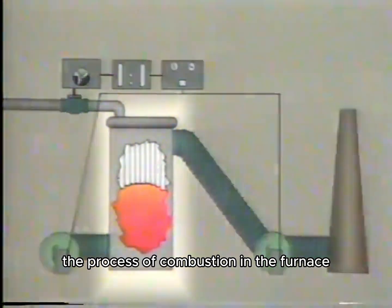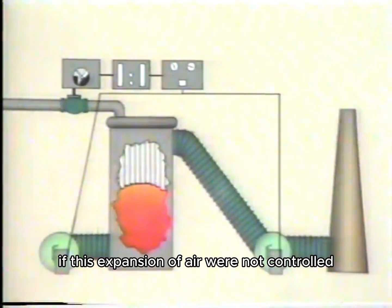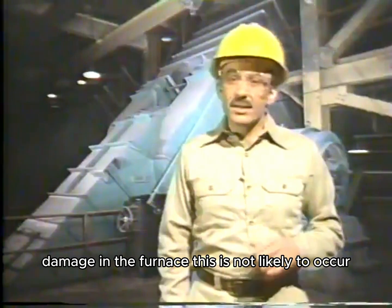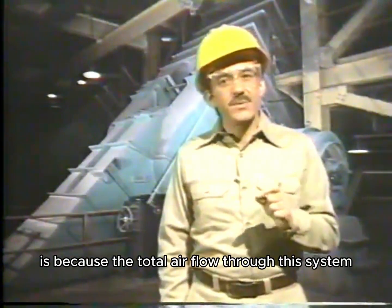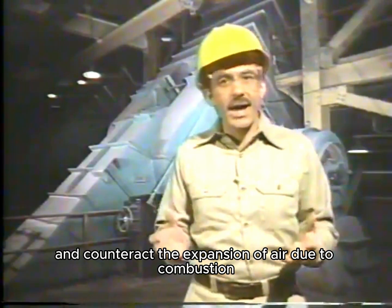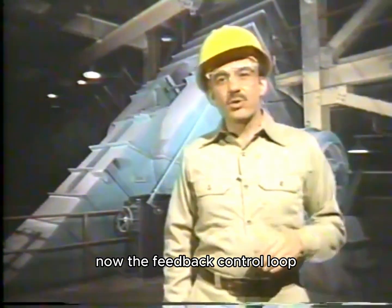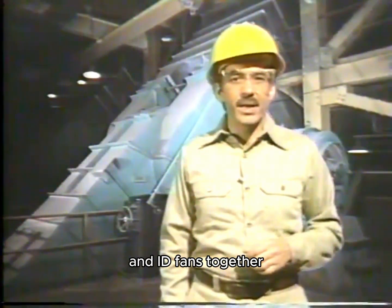The process of combustion in the furnace causes air inside the furnace to heat and expand. If this expansion of air were not controlled, it could eventually cause structural damage in the furnace. This is not likely to occur, and one of the reasons why it's not likely to occur is because the total airflow through this system is controlled to maintain a negative pressure inside the furnace and counteract the expansion of air due to combustion.